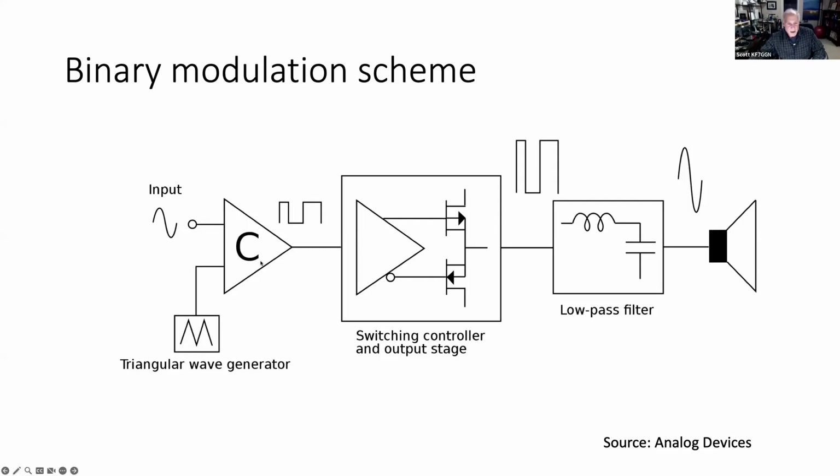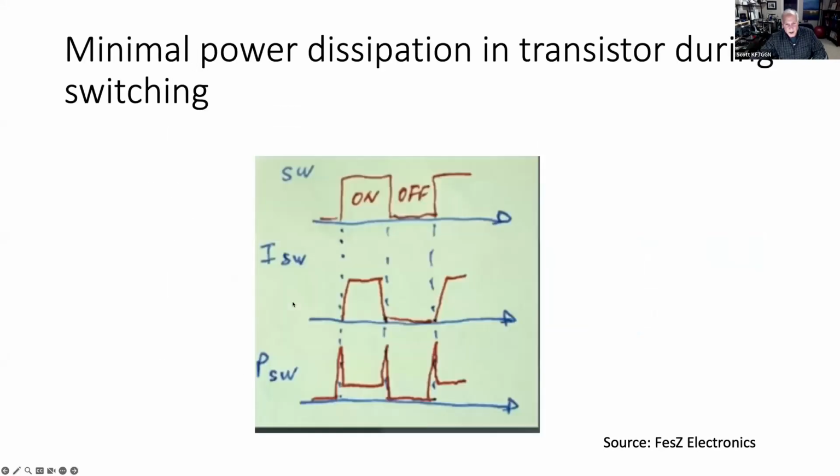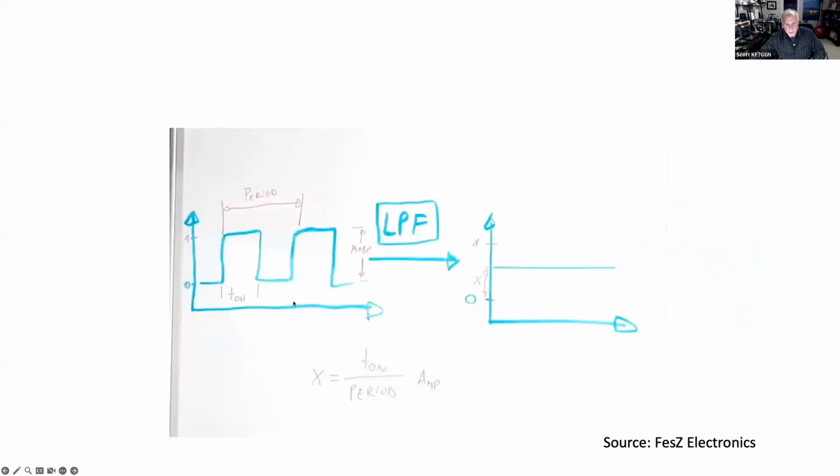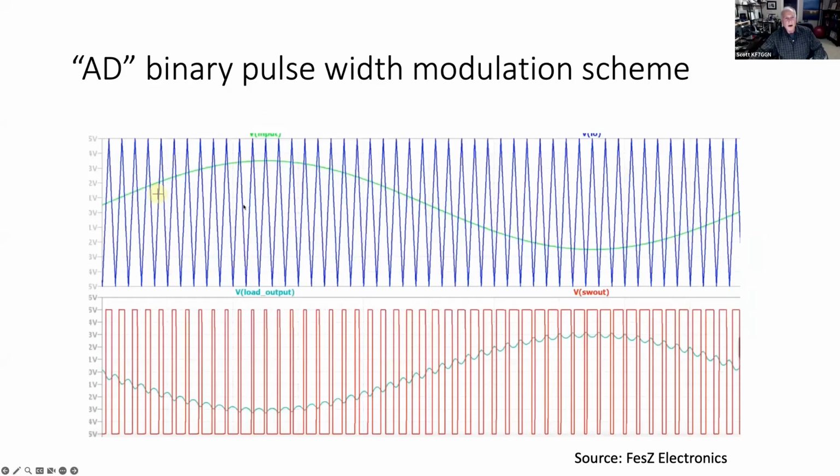And what goes on in the comparator, let me jump to the next slide. Sorry about that. Here. Okay, so in the comparator, what we're doing is we are combining the sine wave here in green, and here the triangle wave in blue. And what the comparator is looking at is, when is one signal greater in voltage than the other signal?